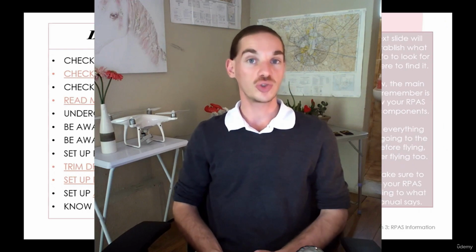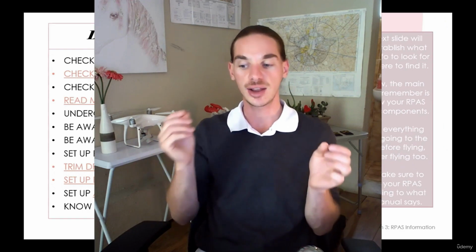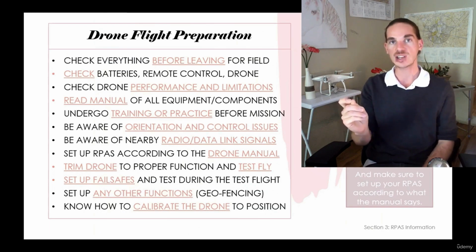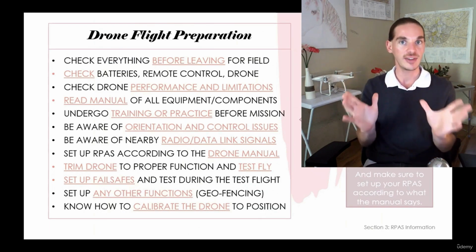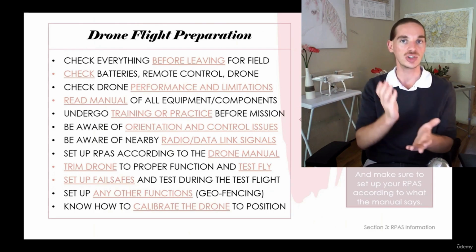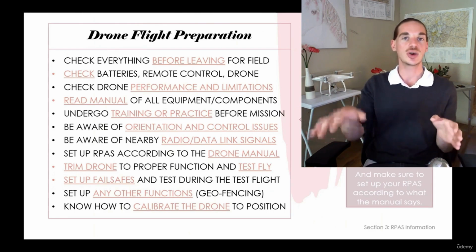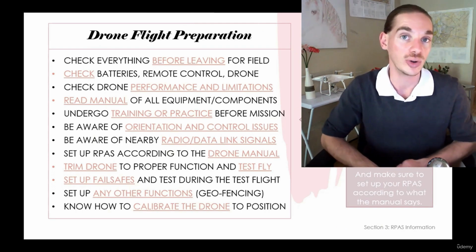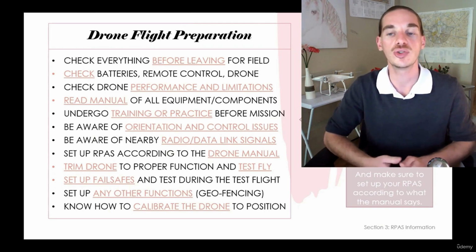And when I'm talking about control issues, I'm talking about things like actually knowing how to control your drone. For example, if you're about to crash into something, simply letting go of the remote control is an important thing to know, because the GPS lock is going to stop the drone automatically. That's dealing with things that are called flight modes, GPS lock mode or position mode.